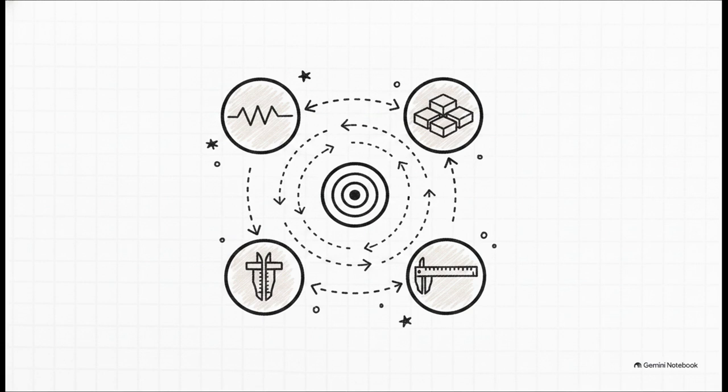You think, aha, I need to modify my compensation network architecture. But wait, that structural change is instantly checked against physical domain constraints. Does this new capacitor physically fit on the layout without introducing some massive parasitic pole? Every single iteration replaces the current bottleneck with a new one, until you finally meet your specs, with margin.